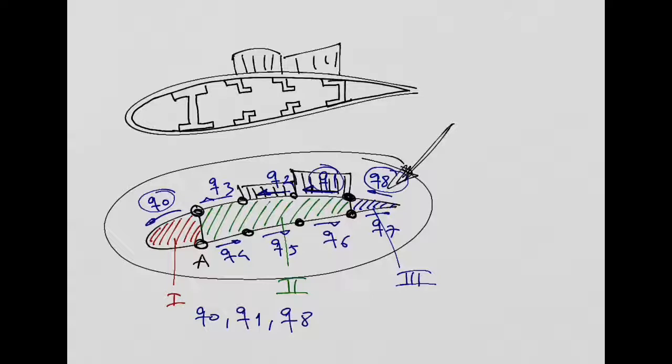Why? Because we have 3 cells. So that will give me only one equation, equilibrium of the moments, but I have 3 unknown shear flows because I have 3 cells. So I need extra equations to calculate these unknown shear flows. These 2 additional equations come from torsion of cross-section. That's why, before we go into idealizing the cross-sections, I need to discuss torsion with you.